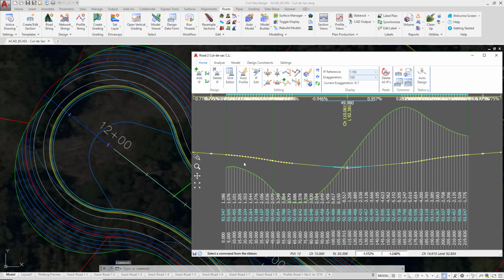As I move my mouse and track along the start of the profile of the vertical grading editor, you can see that the points terminate at the center point. This is the automatic calculation of levels. We told the software to compute the elevations projected from the center line up to the center point change of row 2. We've also got the same happening along the other end.